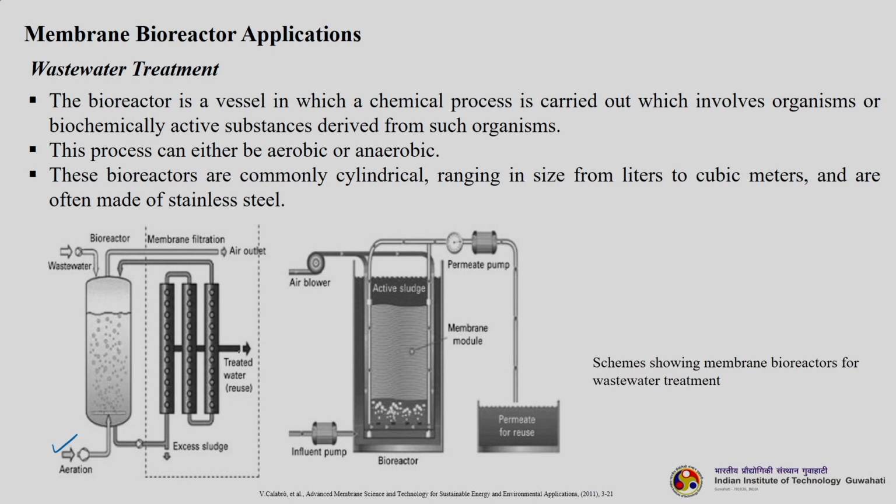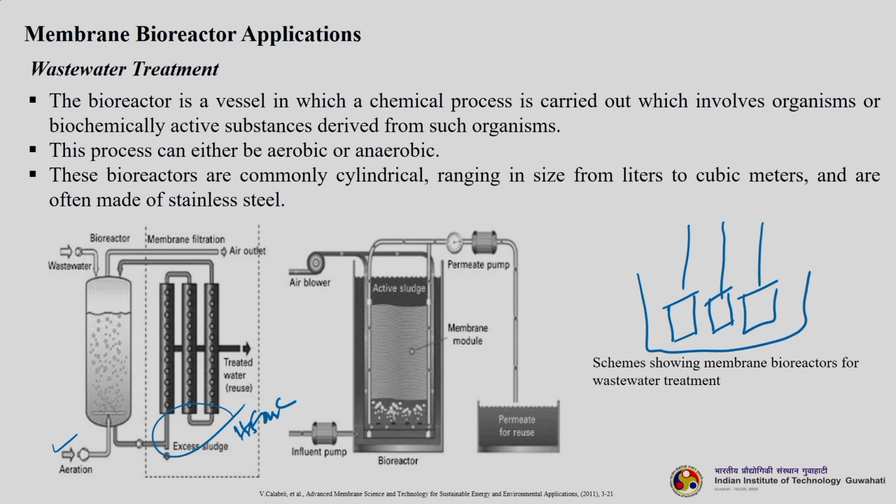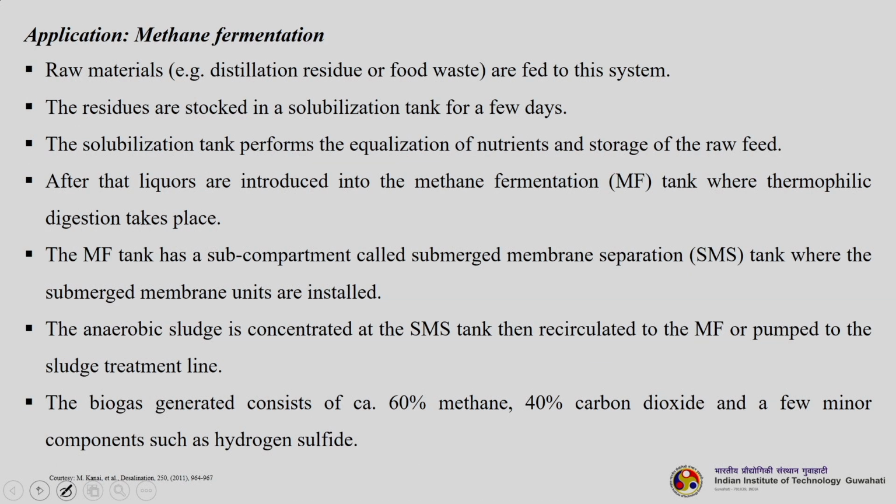So, you can use either this type of hollow fiber, these are HFMC systems, membrane contactors. Okay. So, you can otherwise use plate and frame type modules, okay. Something like this, they are hanged in your activated sludge ponds. Okay. So, this is also possible. It is easy to do, you can take out one, wash it, again put it back, right.